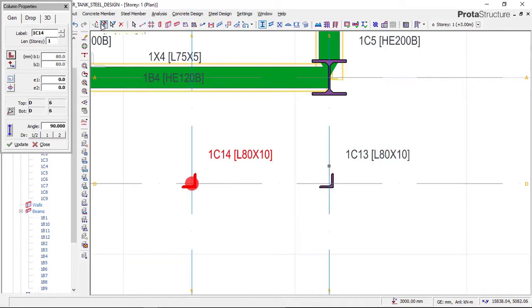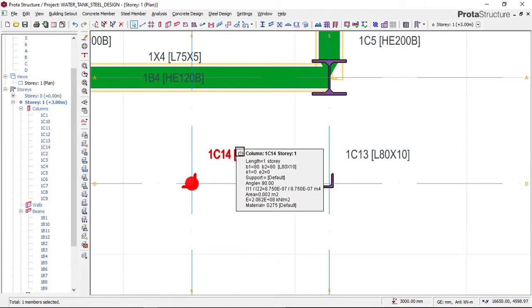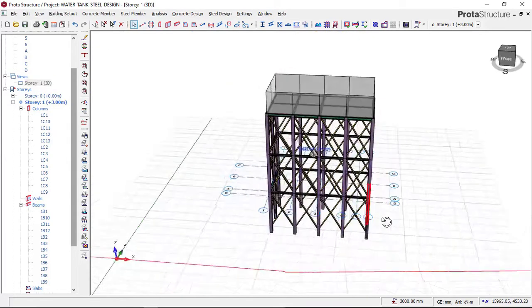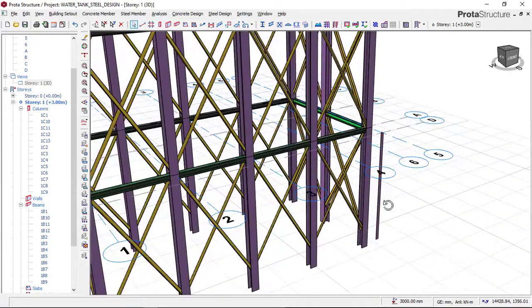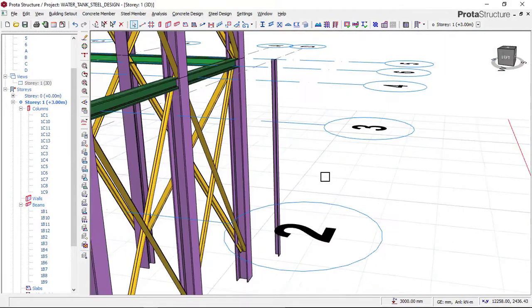Then we'll click on escape. Okay, we can just take this off first. Then after, we will not take the material properties of this to not insert. So if we now check on our 3D view to see what we have just created, you can see what we have just created right now. This is an angle iron for the staircase ladder.